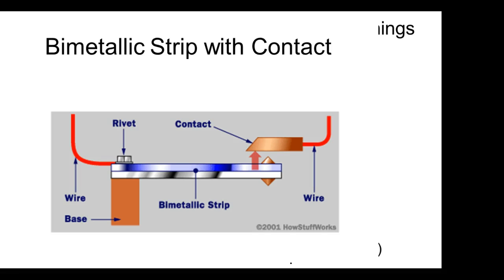So you got a motor out there that's not working, you get out there and don't disconnect anything, get your hands in that blower, and all of a sudden that stuff will reset. It's going to cause you some problems. The bimetallic strips with contact, pretty straightforward.